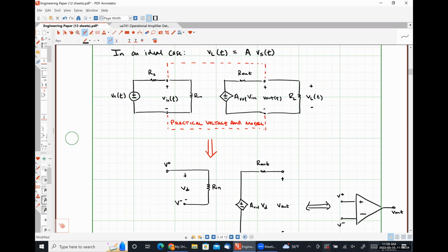Okay, because we have isolation between the input side and the output side, right? So we have this circuit with a ground here, and this circuit with a ground here. We're effectively breaking this ground to allow for the fact that this voltage here isn't ground, but this side is still grounded. And it's because we're physically connecting this device to a power supply that has a ground reference, that is our electrical grid and all of that kind of stuff. So the external power has some zero reference.